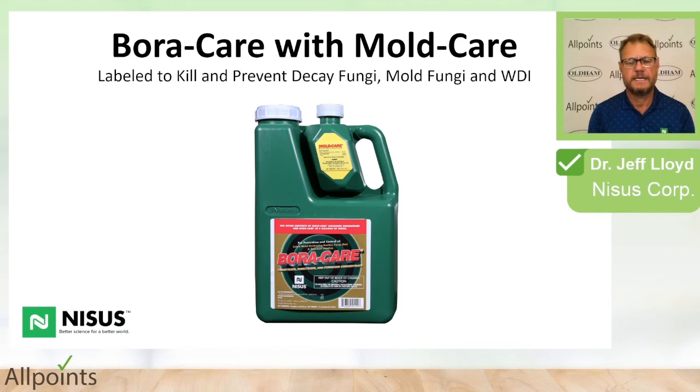Boracare with Mold Care has all of the benefits and penetrating capabilities of the regular Boracare product, and it's combined with Mold Care, our surfactant, bactericide, fungicide, in order to control mold fungi. So the two products together are synergistic against the surface fungi and mold fungi, but you also get the control of the wood destroying insects and wood decaying fungi with the combination of those products.